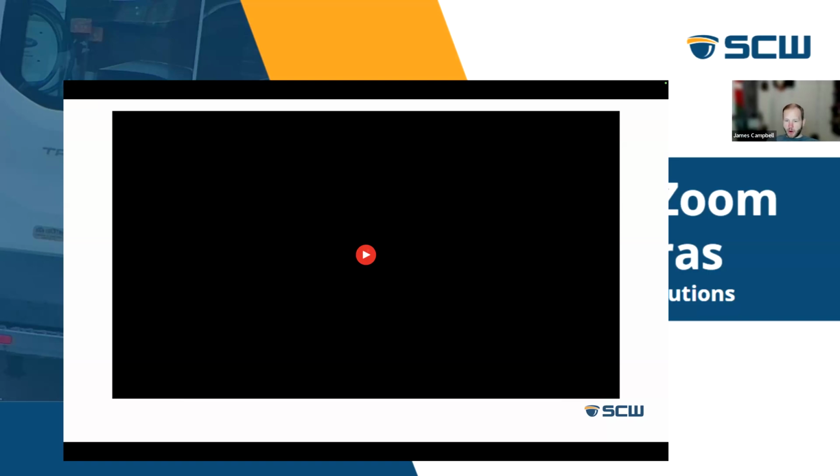And could we increase the priority of auto tracking in terms of different objects and stuff like that? I don't think you can. You can set auto tracking to be triggered by the line crossing or intrusion detection on the actual PTZ. So if you have it pointed at an area instead of on a patrol, you can set it to only auto track when it detects a vehicle or a person. And you can set that line crossing, for example, to only trigger for people or vehicles, or one or the other. You can choose both if you want to too. So that's one way you can get it, but hopefully that answers the question.